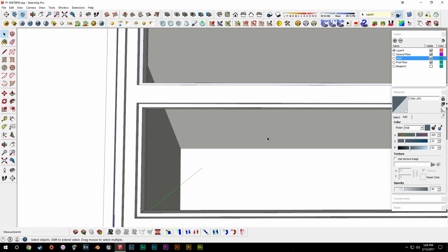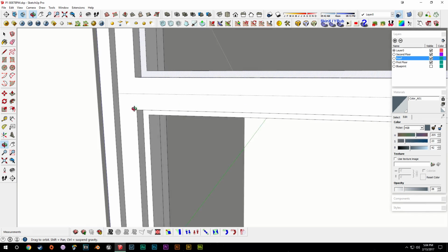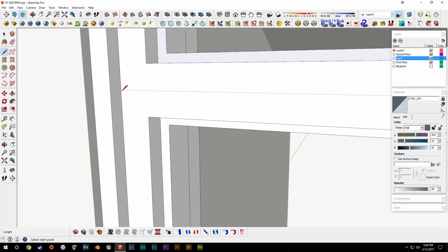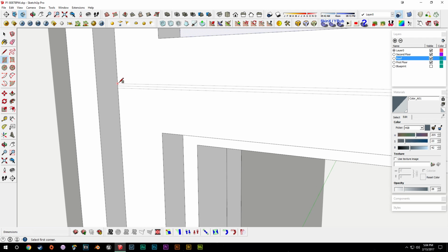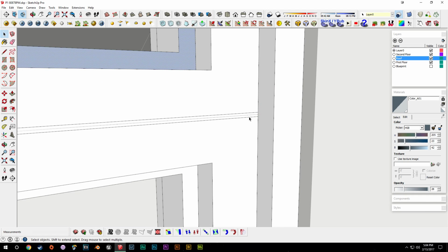And just in case there is a split in this window, I think what we can do is draw a guide here, like that. And instead of drawing in a bunch of new details and adding in the mechanism and all that stuff, we'll draw a line up 1/16 of an inch, and then down 1/16 of an inch. We can drag our rectangle across like that.